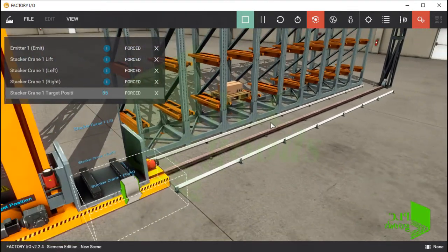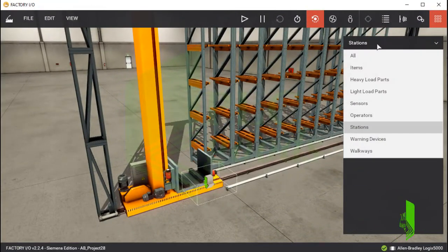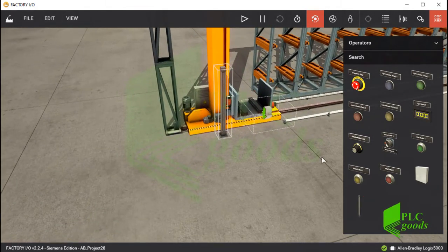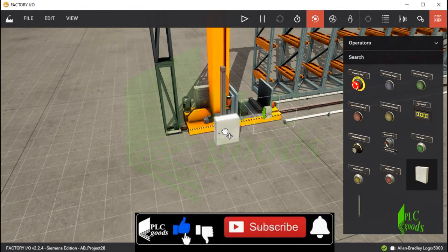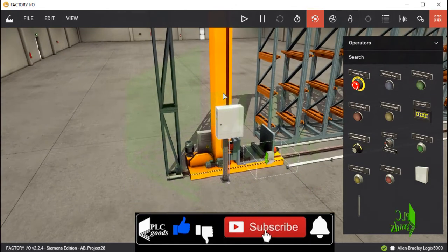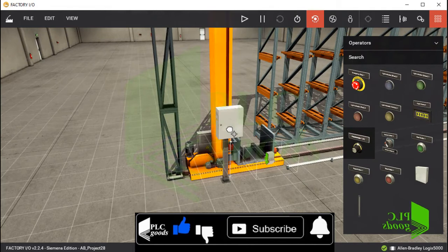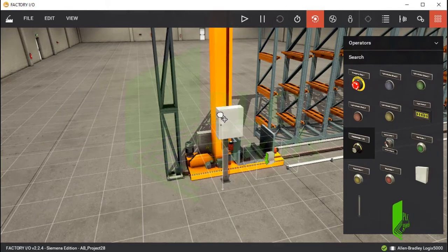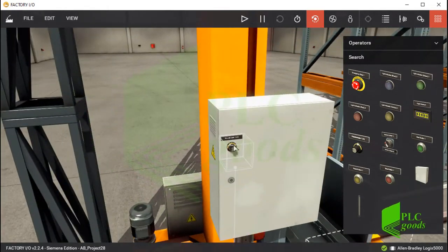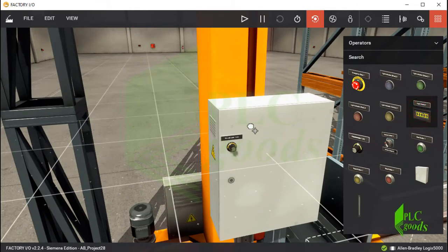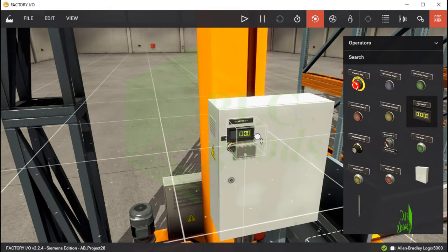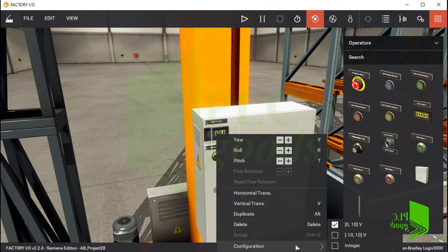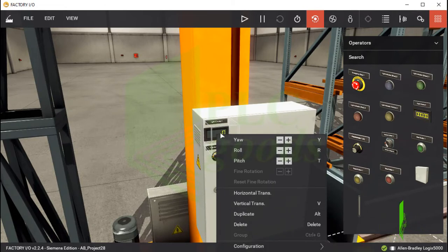Alright, now, let me design a simple control box to enter, store and display 5 positions. First, let me insert a potentiometer. I will use that to select a number from 1 to 54. Note that, the inserted potentiometer voltage range is 0 to 10 volts. So, I must multiply it by 5.4 in my PLC program. Then, convert it to an integer number, to display the desired value on this digital display.